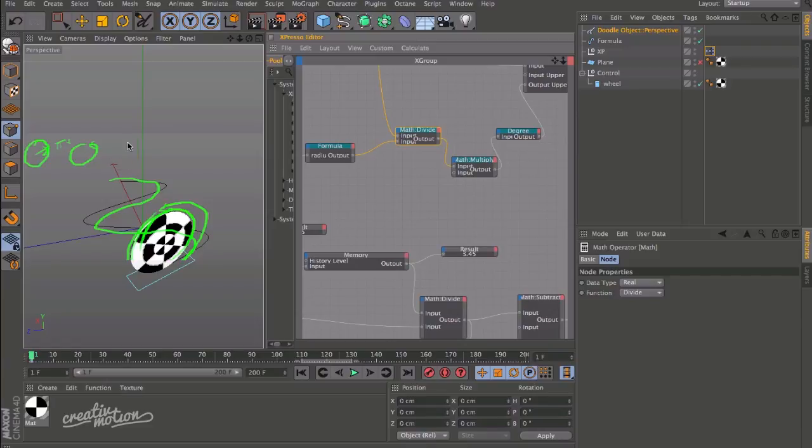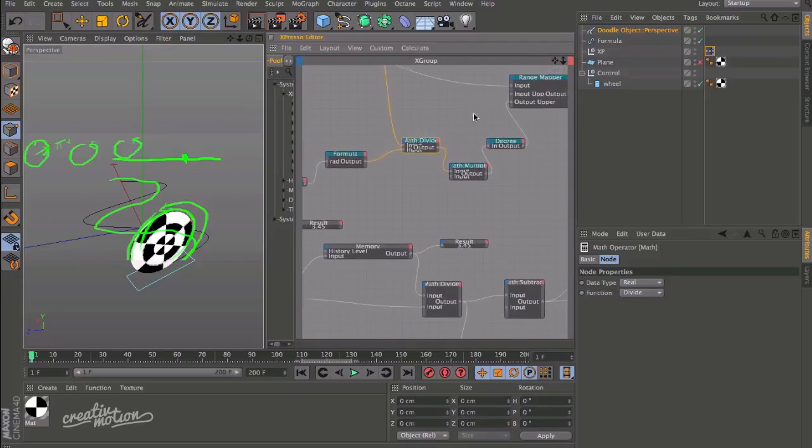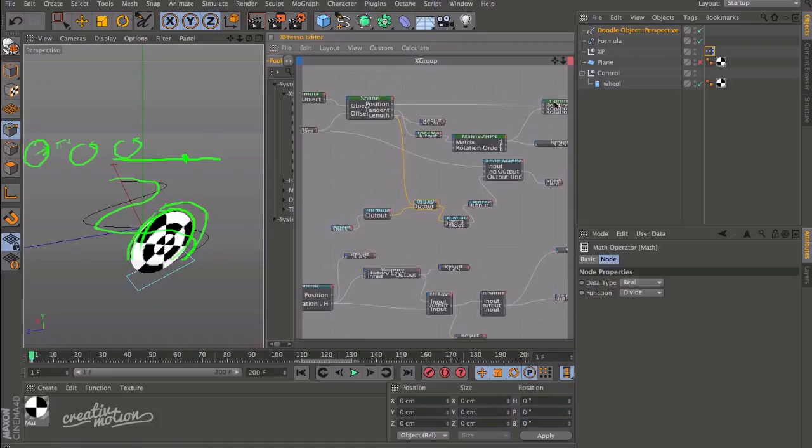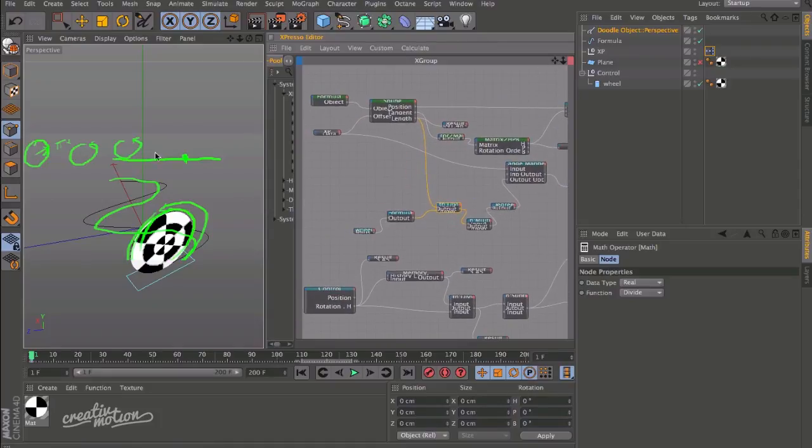So essentially what that's doing is telling us how many times, so you can imagine that we've got the circumference here, how many times, if you were to unfold the circumference onto this total length of the spline, can we fit that onto this? And with this unfolded, it kind of works. It reaches to about, say, here. So I think the value is like 1.4 something, and that then keeps this parametric. So essentially if we change the length of the spline, everything updates.